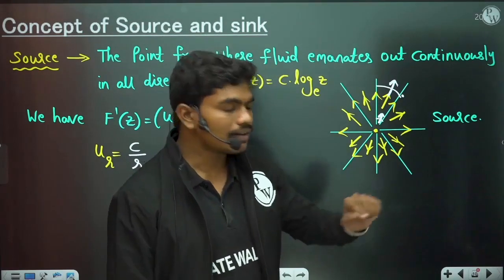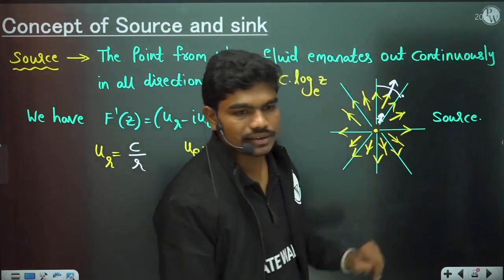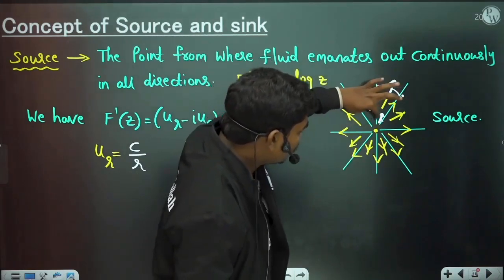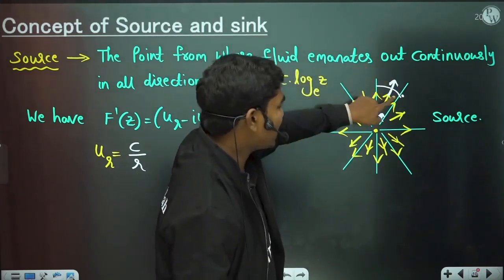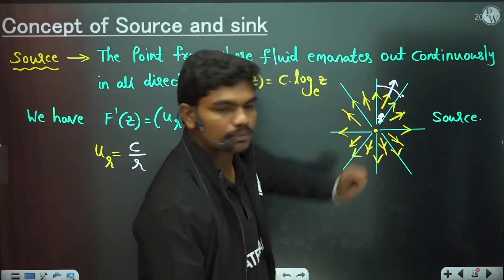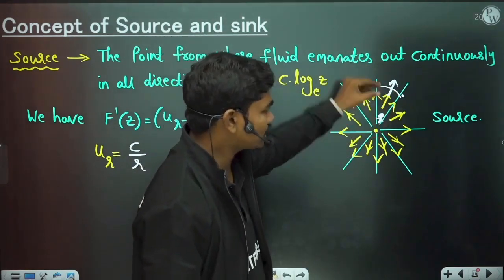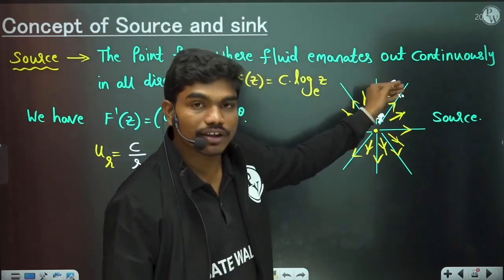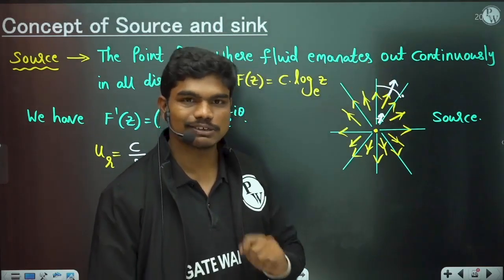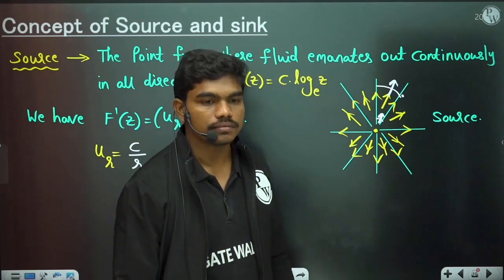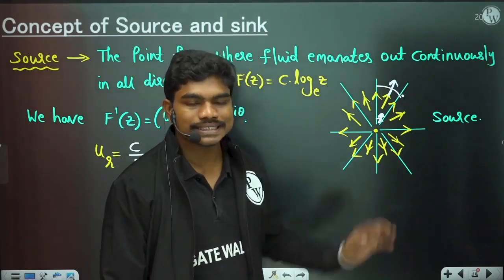Yes. Now whenever the same amount of discharge is crossing, the flow area available between these two streamlines is less as compared to the flow area available at this point, at this higher radius. So whenever the flow area is increased for the same amount of discharge, obviously the velocity of the flow will decrease, yes or no? Correct? Clear? Is this understanding clear to all of you?